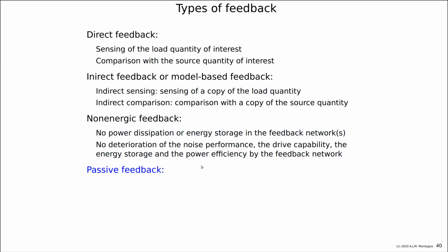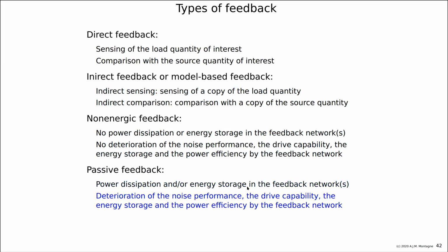This is not the case with passive feedback. If we apply passive feedback, then we are putting impedances in series or in parallel with the signal path, and that will generally cause a deterioration of the performance. It gives power dissipation or extra energy storage in the feedback networks, and it also gives deterioration of the noise performance, the drive capability, and all those other aspects.